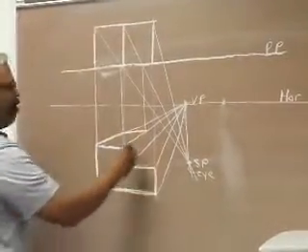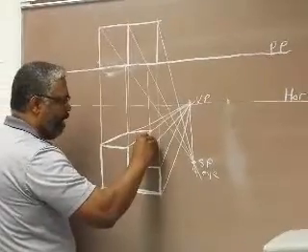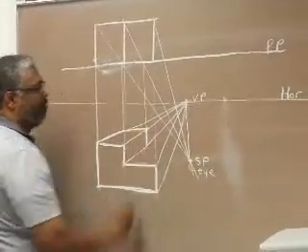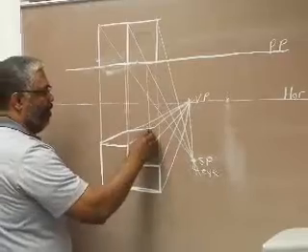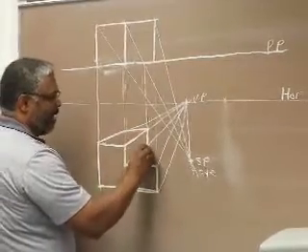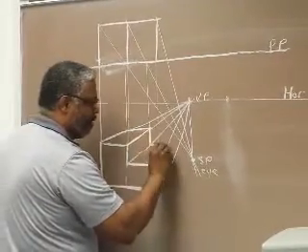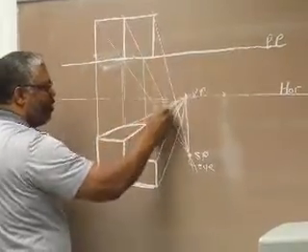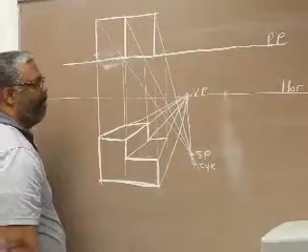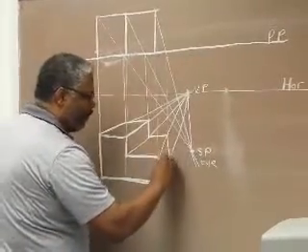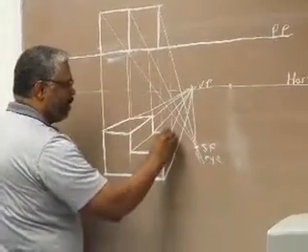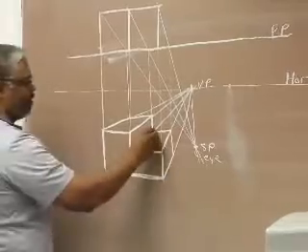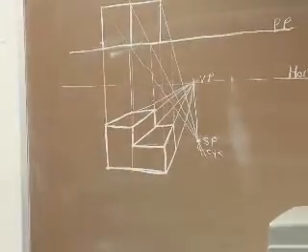So my horizontal dimensions locate that vertical line, and then that gives me that. Since that hits there and this has to be horizontal, that should take me to there. If I do this and bring it down, it should match up. And then that gives me my vertical edge there. And that's, in this case, my perspective of that drawing.